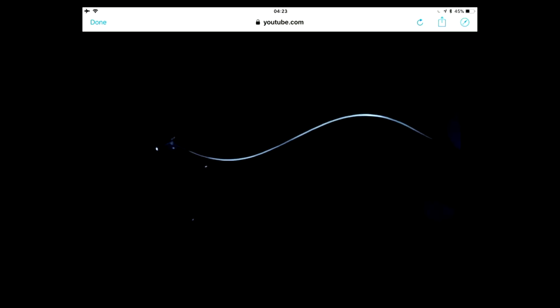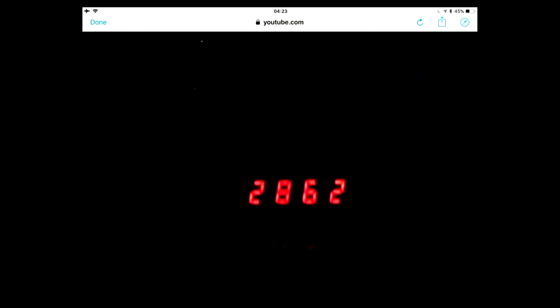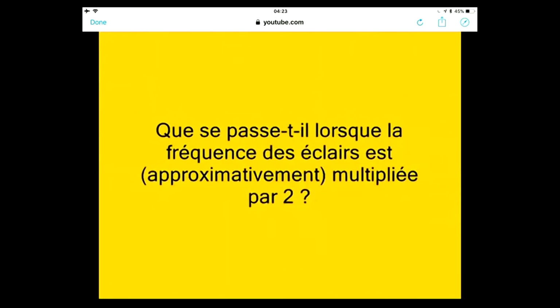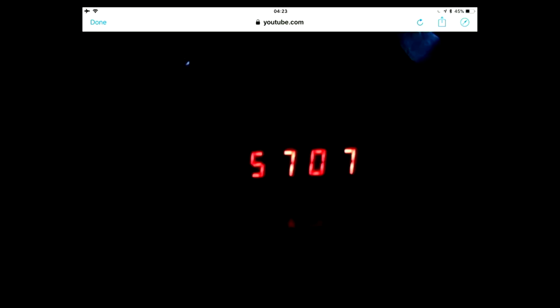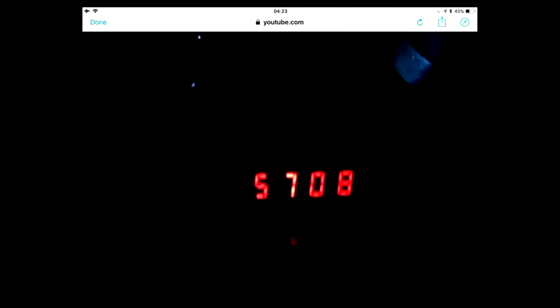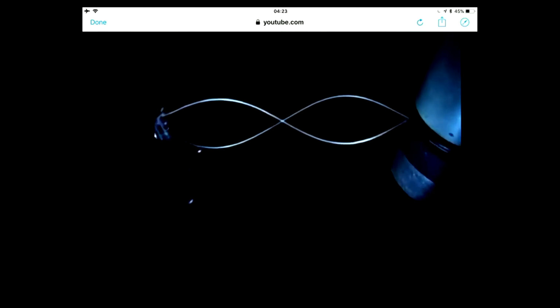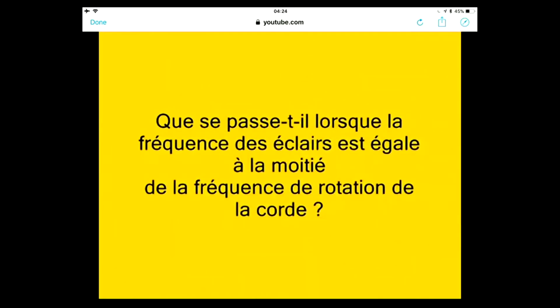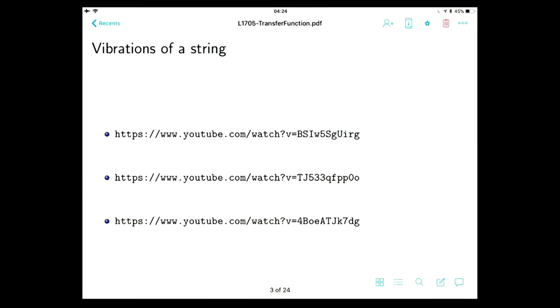So here in musical instrument playing, the notes that you hear are actually the imaginary parts of the eigenvalues of the string or whatever resonant cavity of the instrument, right? How quickly the note decays, that's the real part. And when you look at the string vibrating and what is the geometric shape, that's actually the mode shape, okay? Anyway, I thought that this was kind of a cool way of thinking about mode shapes and eigenvalues and all those things.